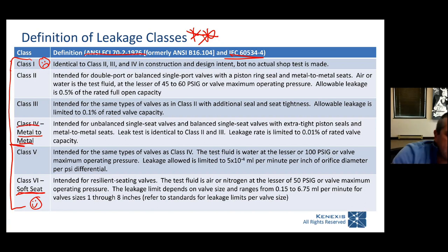Okay, so class 4 ends up being very common in process industries, especially in something like oil refining, because the chemicals in an oil refinery, specifically in a lot of petrochemical plants, are kind of dirty, kind of corrosive. They're a more severe service. So, for instance, if you have natural gas that you're purchasing from a utility, and you're putting that into a boiler, it's extremely clean. You could go ahead and put in that class 6 valve, no problem.